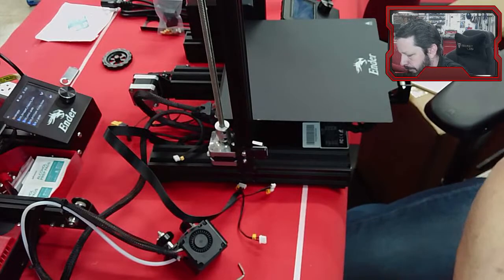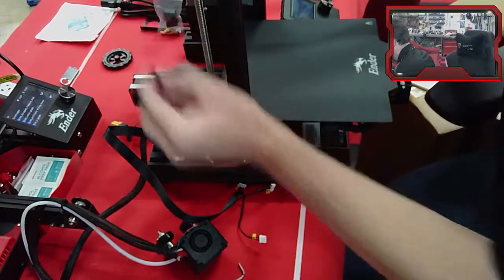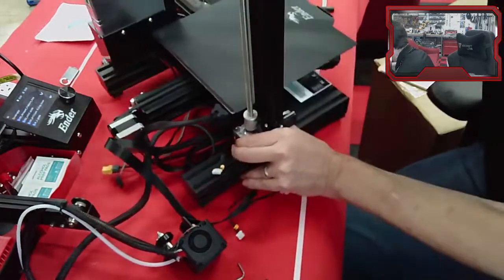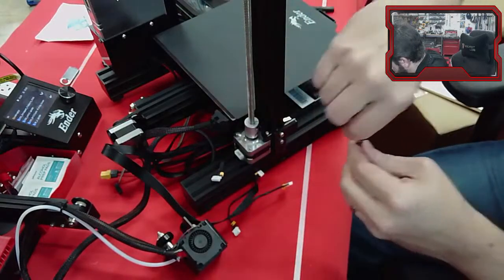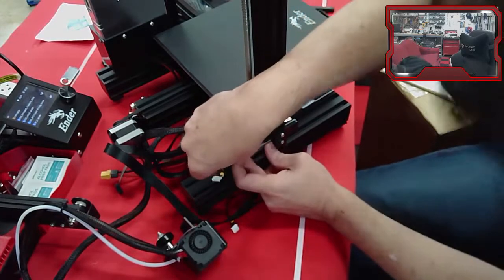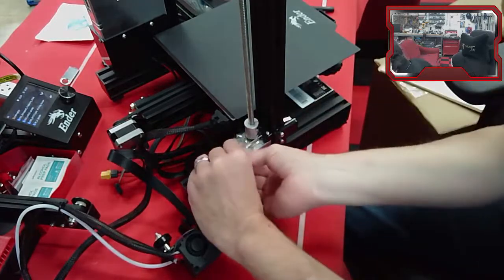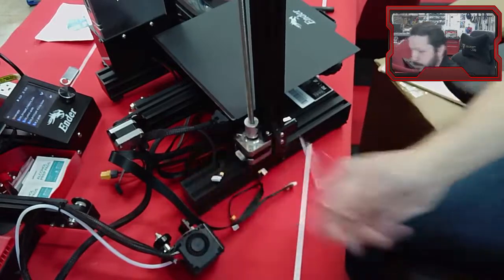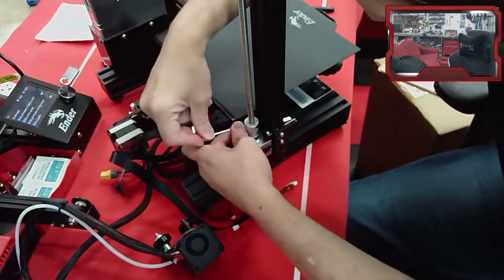So you'll find different versions of this kit depending on how old the kit that you buy is and where you get it from. And they might have slightly different ways of going together. Now I do have to find those holes. There they go. General assembly tip, when you're assembling anything that has more than one fastener, put all the fasteners in and then tighten them up.